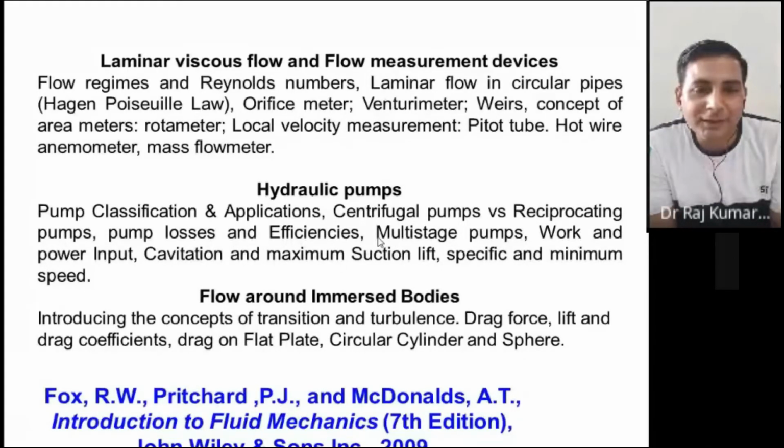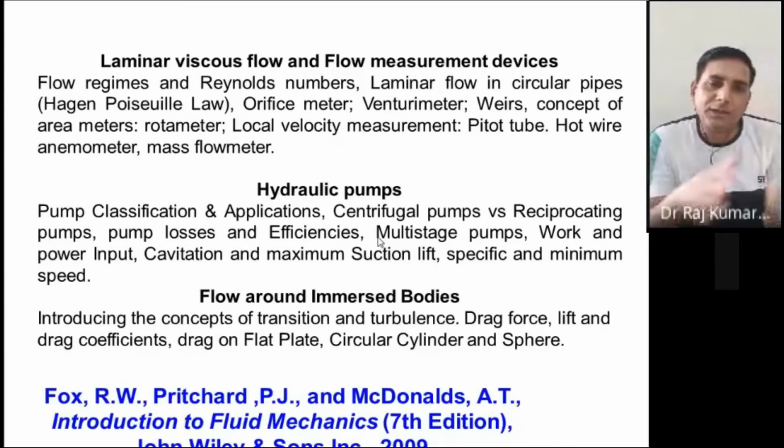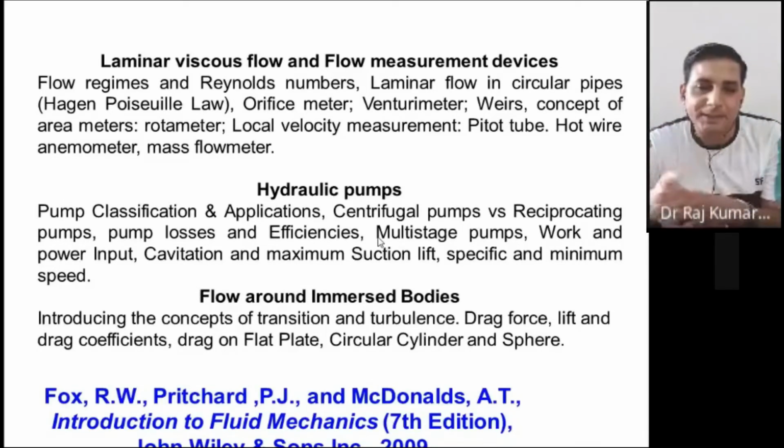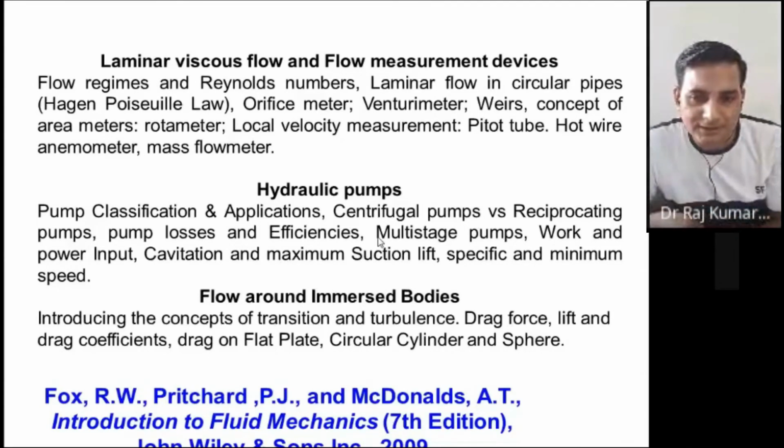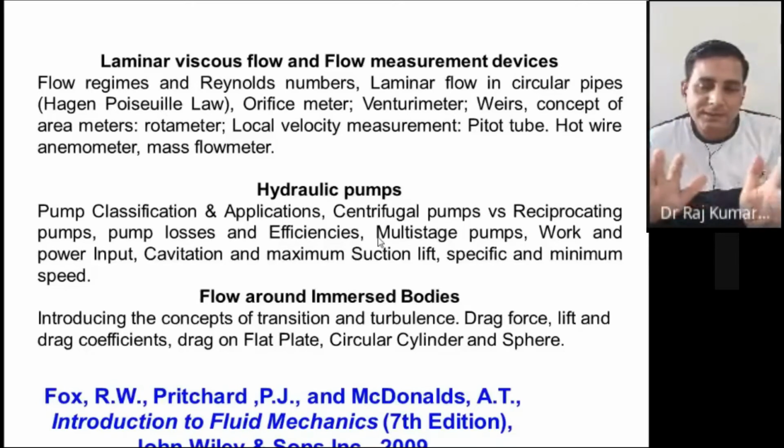So in that case, your quantity always comes in kg because you are not interested in how much the volume is. You are interested in how many kg of gas you are getting, right? So there you need a mass flow meter. Most of the places in chemical engineering we use the volumetric flow rate, because volumetric multiplied by the density will give the mass. But some quantities need to be sold only in terms of mass, just like an LPG gas cylinder. There you are interested in mass measurement, how much mass is being filled in that particular cylinder.